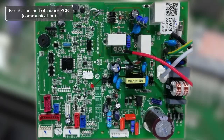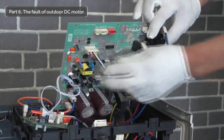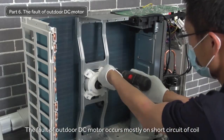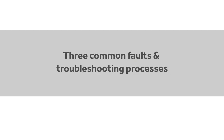Part 5. The fault of indoor PCB. The communication fault of indoor PCB is rare because the indoor temperature and humidity are relatively constant. Part 6. The fault of outdoor DC motor. The fault of outdoor DC motor occurs mostly on short circuit of coil that causes no 5-volt voltage input to outdoor PCB. 3 common faults and troubleshooting processes.